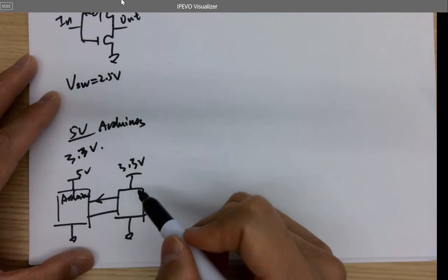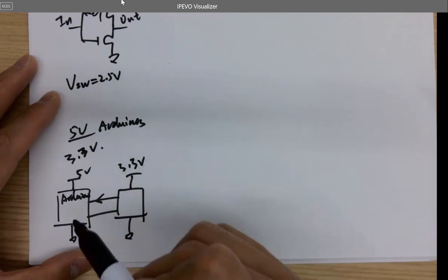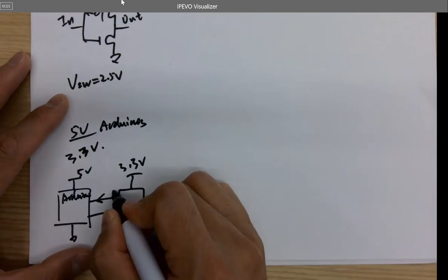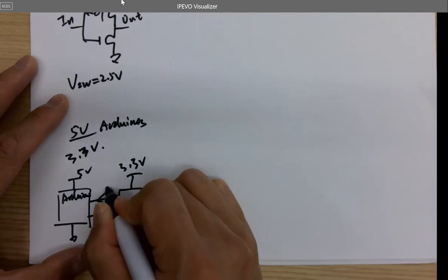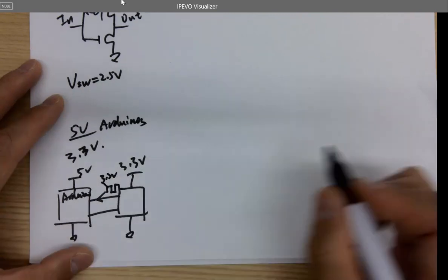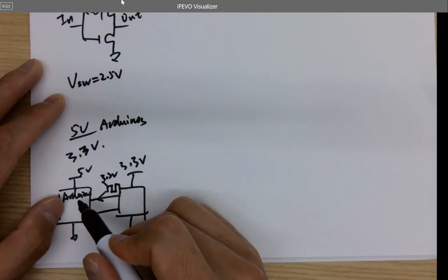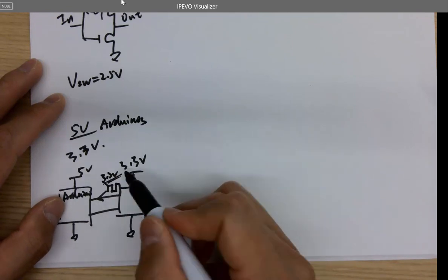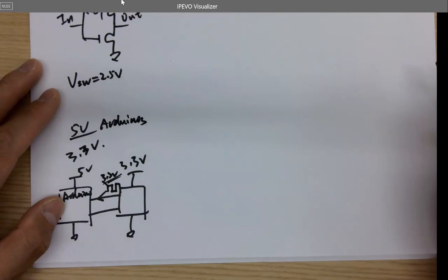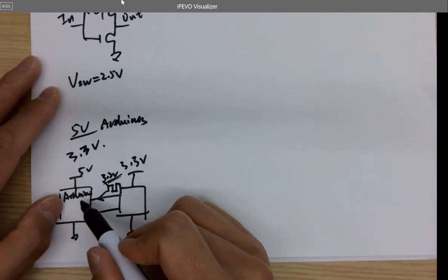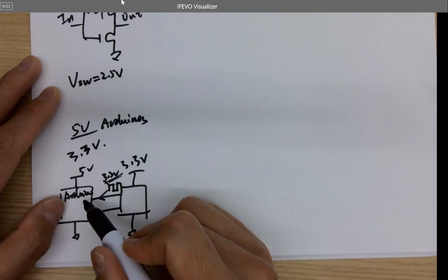You can connect the 3.3 volt sensor to the Arduino, which is fine. Because this one will send signal, which is 3.3 volts at the maximum, as logic 1, to this guy. So the transistors designed in Arduino can handle that logic 1, which is 3.3 volts, no problem. It won't damage it because these transistors are designed to run 0 to 5 volts digital signal, right?